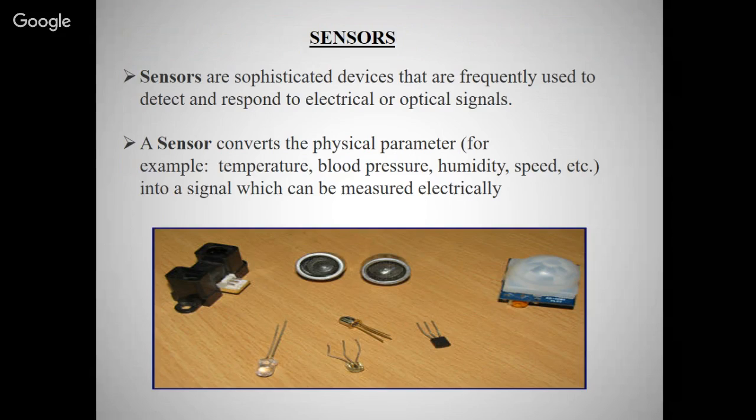When the light changes, the resistance is different, and we are continuously reading the values of the resistance, and the values keep changing. If LDR1 has the higher value and LDR2 the lower voltage, then we rotate according to that. So this is the sensor we have used, the four LDR sensors with the potential divider circuit.